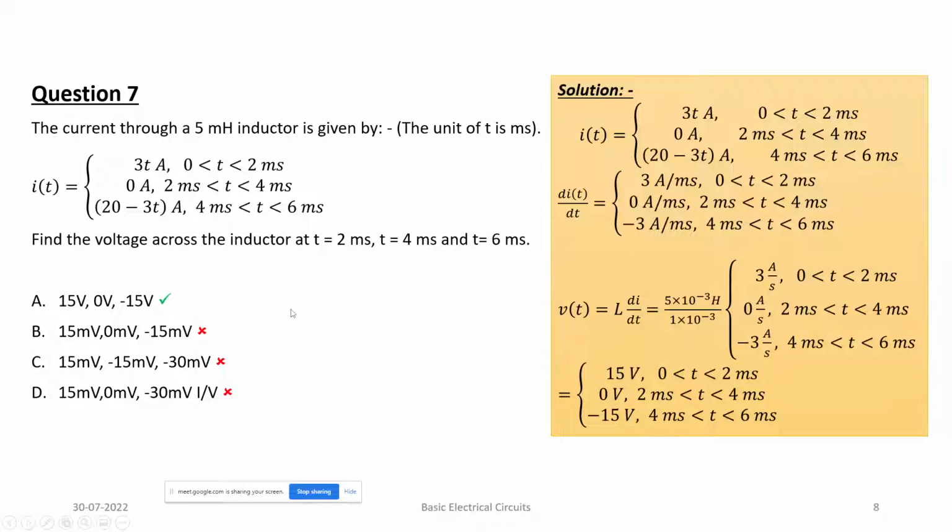So it actually is derived from the basic definition that inductance is the constant of proportionality between the magnetic flux linkage of the coil and the current through the coil, and the Faraday's law. The Faraday's law states that the voltage is proportional to the rate of change of flux linkage. So if you consider V equals d psi by dt, or minus d psi by dt if you consider Lenz's law, and psi is L into I, then if you combine these two, we get V(t) equals L di by dt. Okay. Is it clear?